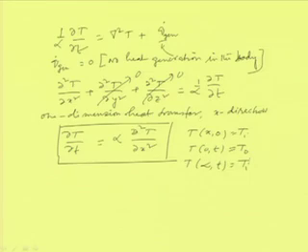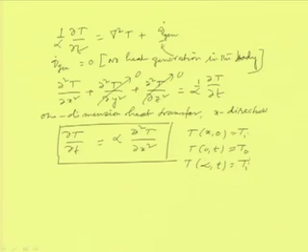Now, we can understand this is a partial differential equation. There can be several ways to solve this partial differential equation for getting an analytical solution. There can be a numerical solution also, but we are not interested in a numerical solution at this moment. We will be discussing the analytical solution, to see the temperature profile. We will assume that there are two independent variables in this equation, which are time and x. What we will do is go by the method of combination of variables.